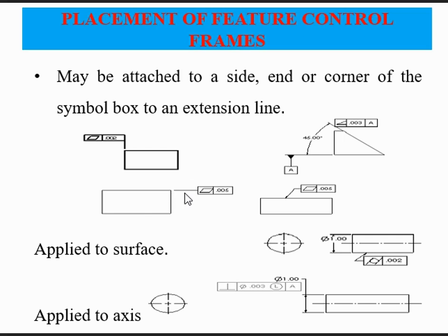That is shown in the form of a GD&T symbol like this. See, this symbol is of flatness and second is the tolerance. This feature frame is talking about the geometrical aspect of this rectangular plate, that is flatness. While maintaining the flatness of this object, the tolerance should not exceed the value of 0.005. That is what the person who has made the drawing wants you to know.